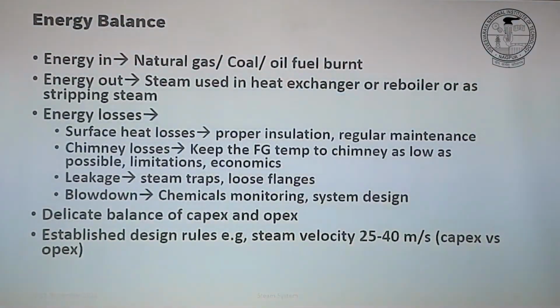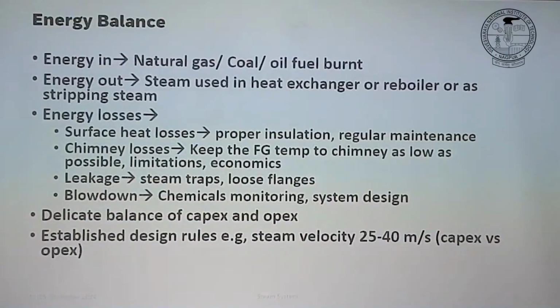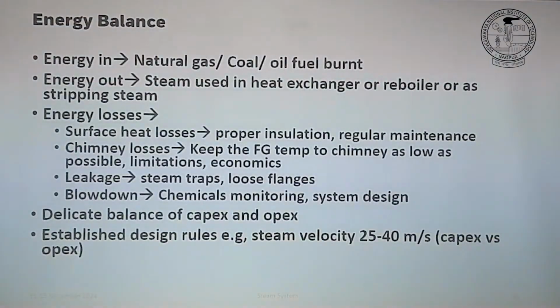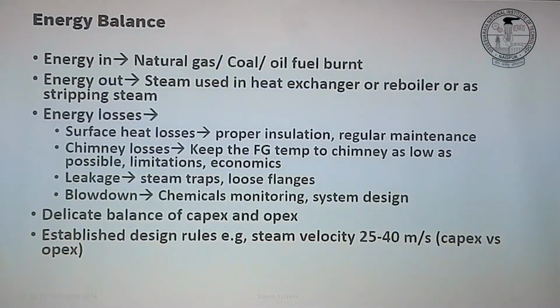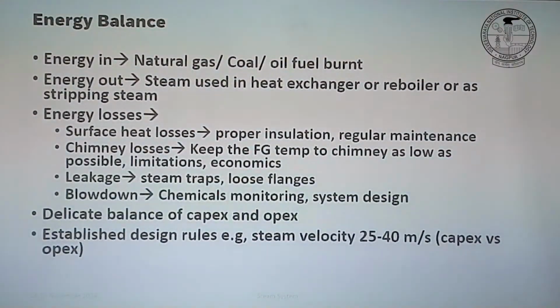But high velocity also means you need a very small pipe, so you can save on capex. Area is small, and area is nothing but money, because area times thickness is actually what you pay for. I think it also satisfies the equation of continuity. So if we decrease the area, the velocity will increase, which means squeezing the pipe. Yes, so area means the flow area, the diameter. Smaller. Yes, exactly. So it's always a trade-off between capex and opex.